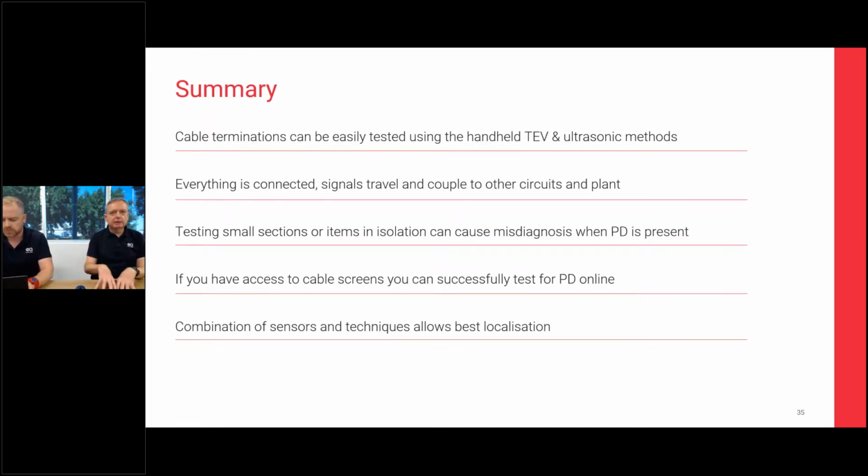It can be true at times that you get indications of partial discharge on cables, and you can't, just from online techniques, come to the most specific answer, such as what Brad showed, which is that the cable joint 20 meters up is discharging, and that cable joint will fail soon. Sometimes you do need to take an outage and do offline testing.